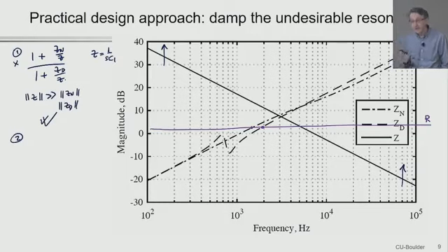We can, however, exploit this idea of trying to cross these impedances at a flat line and arranging what we call a damping network so that we preserve the properties of the SEPIC converter normally operating, minimize the power loss, and yet, in this range of frequencies that we're looking at right now, make that extra impedance look resistive. Okay, so how do we do that?